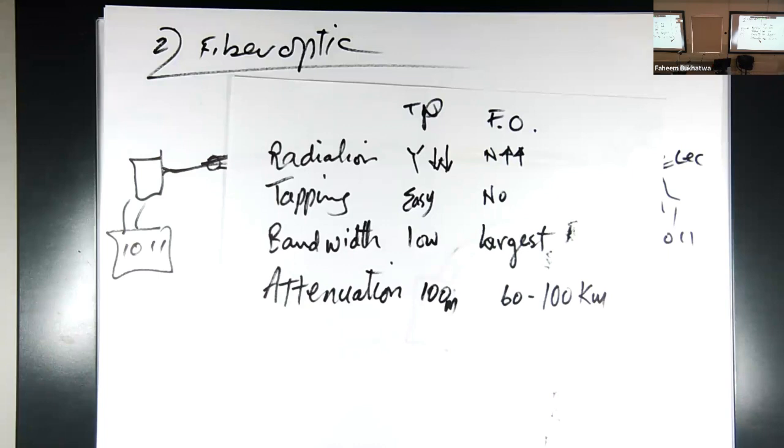Your repeater is like an injection of more energy, right? No, that's probably an amplifier that will inject more energy. Technically, the repeater will analyze the older signal and generate a new signal based on that. For example, the signal should be +5 and -5, but by the time it gets to the repeater, it probably reads +1 and -1. It says, oh, the +1 is really +5, so it immediately converts the +1 to +5 and the -1 into -5. But it runs on something. Pardon? It runs on power. Yeah, it needs electric power. Oh, definitely, a repeater will need some power, yeah.